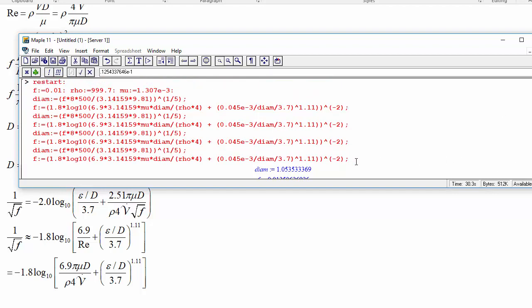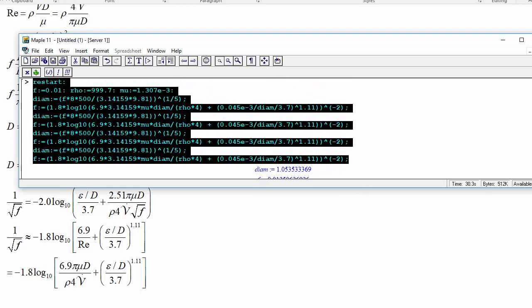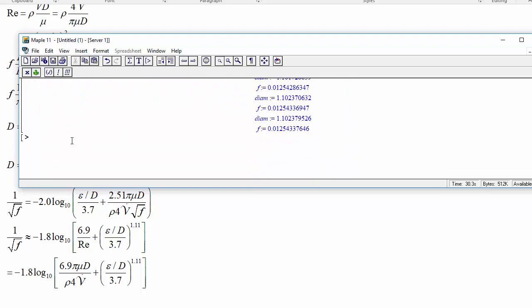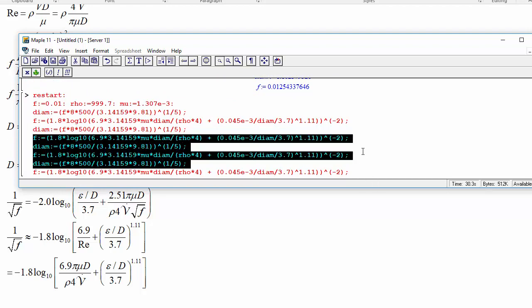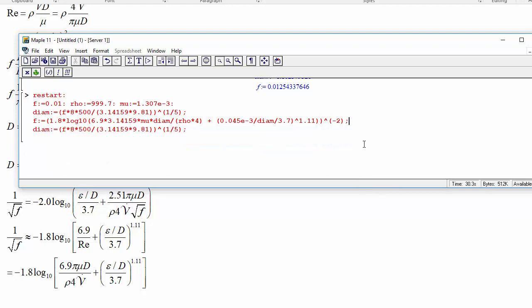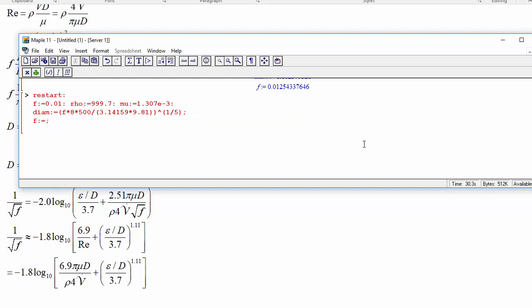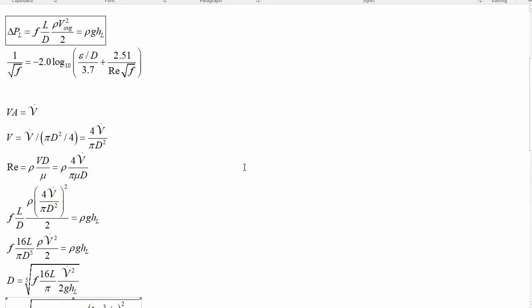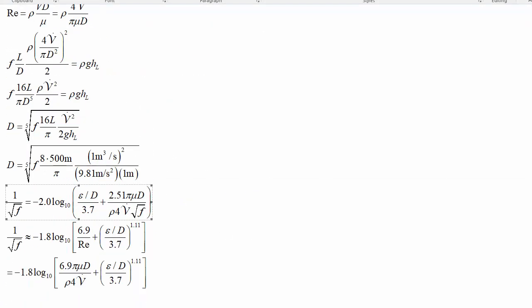If you wanted to know how much better or how much worse this is than the Colebrook equation in this case, then we can do another version of the problem where we use the Colebrook equation. So how would that be different? Well, for this step, instead of doing that, what we'll do is solve the explicit equation. You could include some iteration on that.